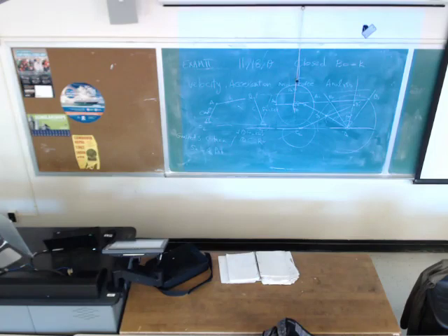This is O2, this is A. Link B should be between these 2 points, but it doesn't have to be a straight link. It can be something like this. It's not going to change the motion of the mechanism as long as you have these 2 points fixed. And this is going to be link 4. This is the location of O4, B, A, and O2.